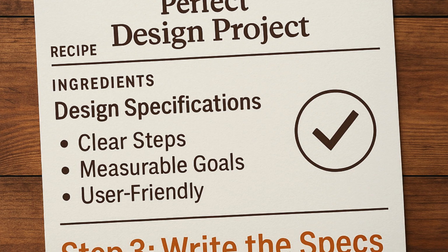5. The design style. Ask yourself, what does it look like? What mood or feeling does the design convey? Is it modern, playful, minimalistic, or professional? The aesthetics greatly influence user satisfaction and desirability. 6. We talk about the ergonomics. The ergonomics refers to how comfortable and how user-friendly the product is. Analyze factors such as the grip, the handling, the weight, the interaction, the comfort, and the ease of access.